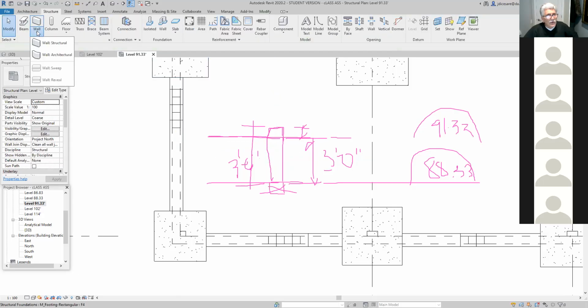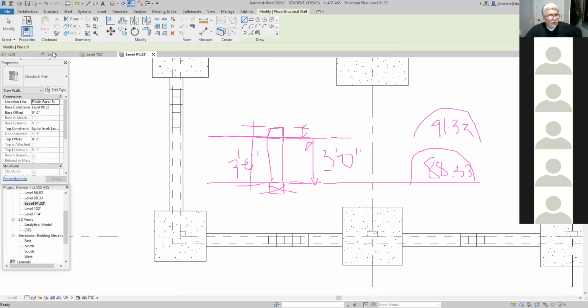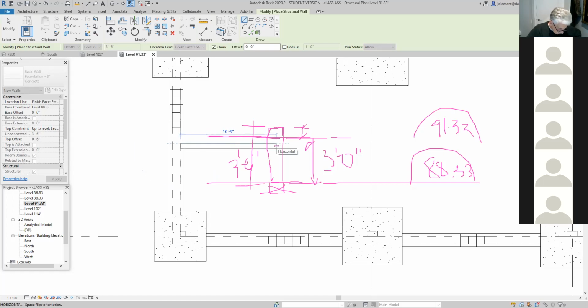I was looking at the drawing and I wasn't looking at my drawing area. Structural wall, 8 inches. Everything stays the same, right? Nothing's changed. Yeah, I double checked that. Exterior face outside. Like I said, I drag up from that point there. Now I can drag up until I see 12 on the screen, or I can actually put in 12. Okay, I go over by 10 feet. Sorry, yeah, that was doing it correctly. I'm going to go over by 10 feet. Enter. Then I'm going to come down and just intersect that wall again. And if I'm happy with that, I press escape.